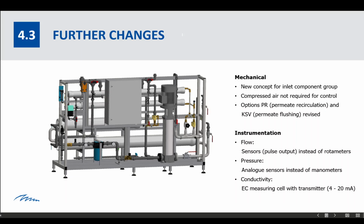The instrumentation has changed. We have new flow sensors with a pulse output instead of rotor meters. We have new pressure sensors, we have analog sensors instead of manometers, and a new conductivity measurement with transmitter to 4 to 20 milliamps.